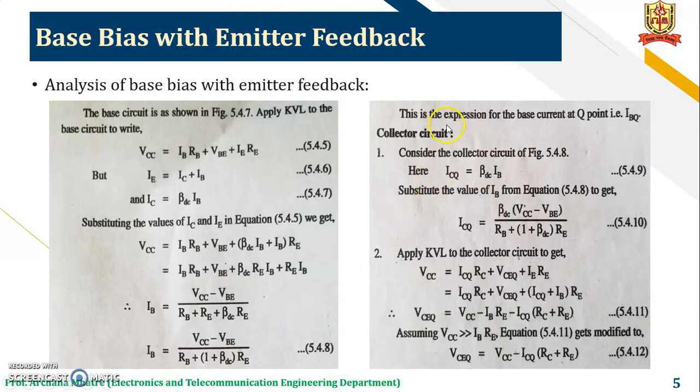Now expression for the base current at the Q point, that is IBQ. Here we will apply KVL to the collector side, that is the output side. So we'll get the equation VCC is equal to IC RC plus VCE plus IE RE.